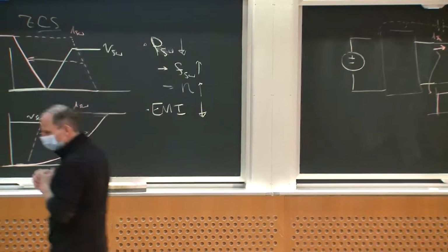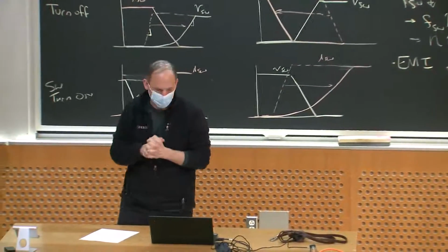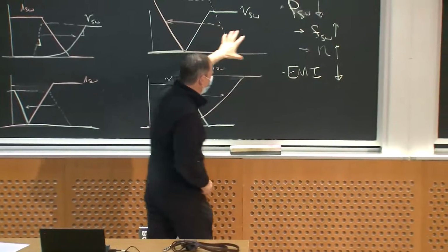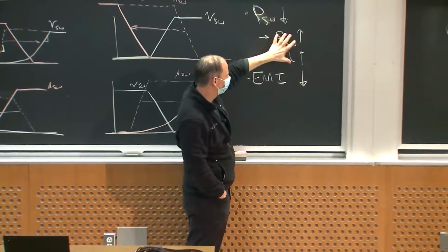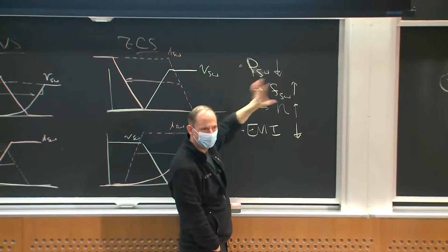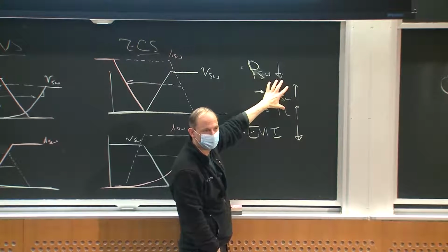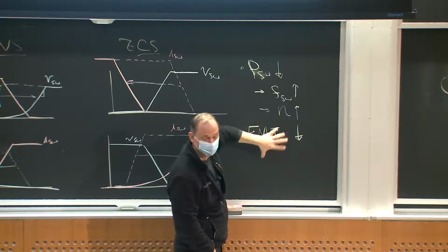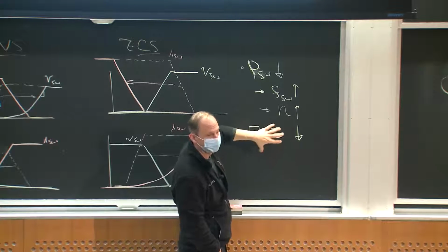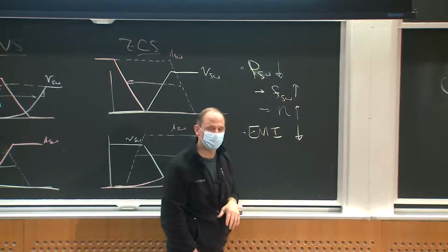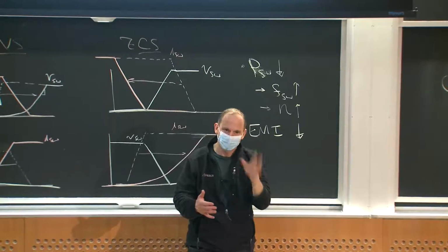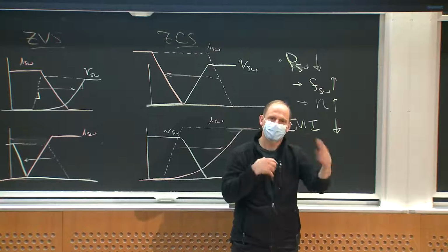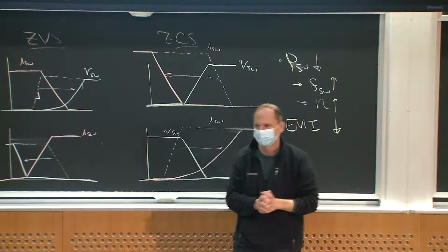Okay, so I wanted to argue that one of the things we can get out of soft switching is reduced switching loss, which lets us either get efficiency or higher frequencies, and hence possibly higher power densities, smaller component size. And for a given switching frequency, we reduce the EMI. And even when you're pushing frequency, that can help you, because you might have a high switching frequency converter that doesn't have increased really high frequency content. Okay.